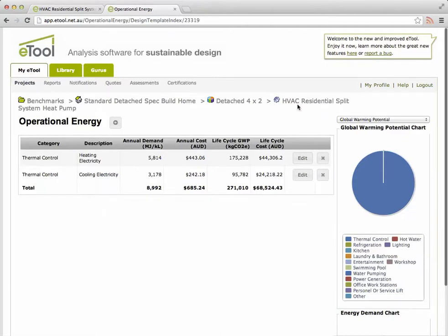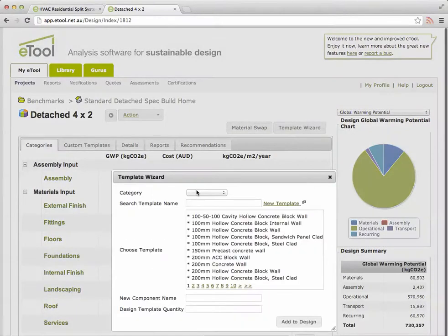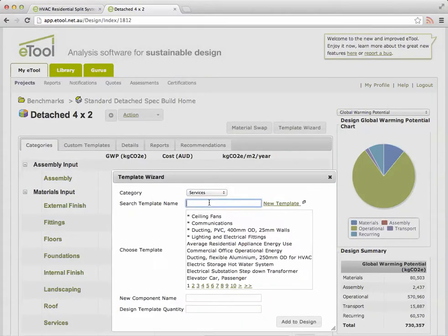A couple of things to be aware of. If we loaded up 3 air conditioners into this building, the heating load just relates to this information here. It does not relate to the number of air conditioners. It relates to the conditioned space of the building, and many of the heating and cooling devices, if we just go and have a look at that list, are only actually heating or cooling.